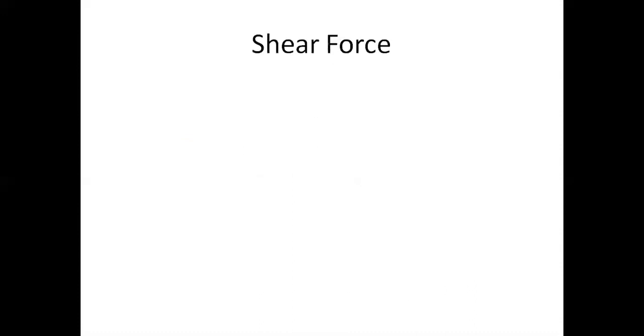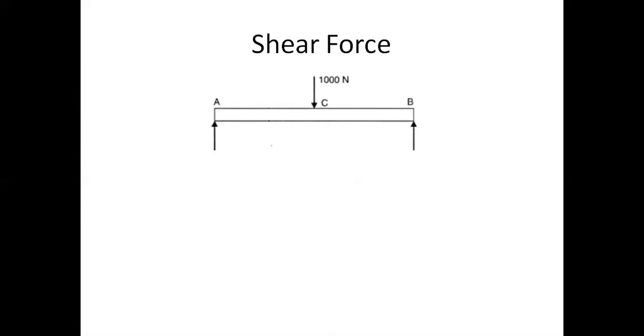Now we will come to what is shear force. Before we define what exactly the shear force is, let us consider a beam. Now what kind of beam is it? Yes, you guessed, you have two supports here. And what type of load do you have? A point load here. So this beam is a simply supported beam because it has two supports at both the ends, and also you have a point load at the center, for example.